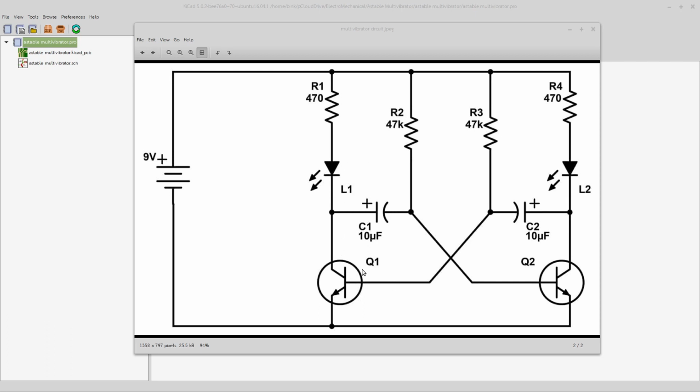So then they would say that, okay, it triggers, and then this starts flowing. What then begins to happen is this capacitor starts charging, and I don't really want to fill you full of erroneous information. I just want to tell you the problem that I was having. They were saying that the capacitor will start to charge here, that is for the base of this transistor, okay? Then eventually this transistor would charge up to 0.7 volts. It could go all the way up to, like in this case, 9 volts, whatever the VCC is, almost. And anyways, it will get up to 0.7, and that'll cause Q2 to trigger.